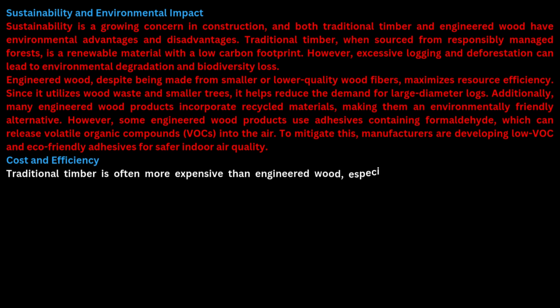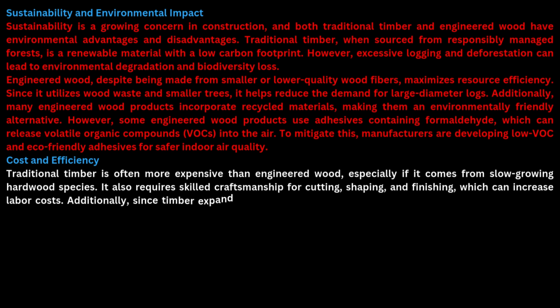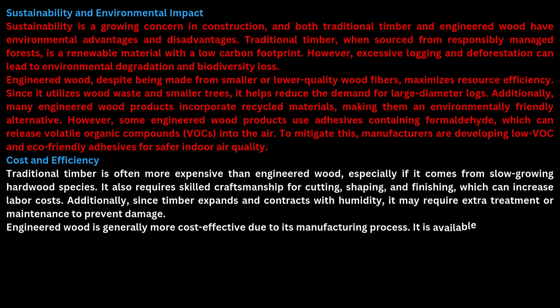Cost and efficiency. Traditional timber is often more expensive than engineered wood, especially if it comes from slow-growing hardwood species. It also requires skilled craftsmanship for cutting, shaping, and finishing, which can increase labor costs. Additionally, since timber expands and contracts with humidity, it may require extra treatment or maintenance to prevent damage. Engineered wood is generally more cost-effective due to its manufacturing process.